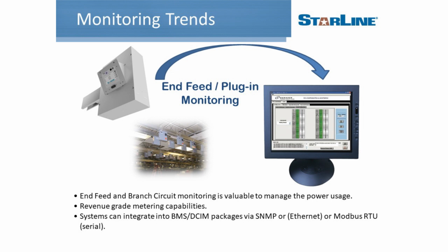The other thing that we continue to see, and it's on everyone's mind, is the monitoring trends. Once again, we talked earlier about being able to track power usage and understand your facility and how that is incorporated, being able to get revenue grade metering from both an end feed to monitor the entire busway run, and then at your rack level is definitely something that we continue to see trending, and it's actually been quite substantial over the last couple of years.